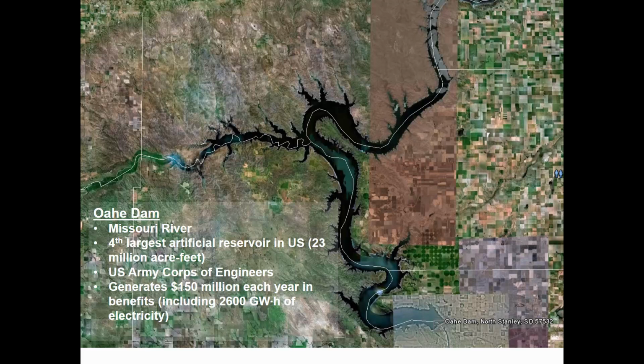So then if you wanted to convert between acre feet and cubic feet, what you'd do is, we know there are 43,560 feet squared per acre. So if you had 1 acre foot, then that means it is an acre of area and a foot of depth.